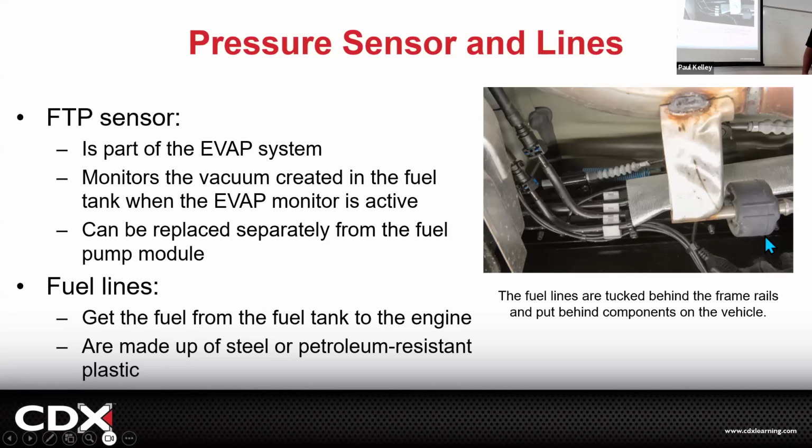Give you a clue. It's got to do with this rubber thing and this thing. Is it just me, or does that look like an exhaust hanger? So if we got fuel lines near the exhaust, is that sketchy? It's normal, sadly. I mean, I'm a little scared, but we run a protective heat shield around the fuel lines to keep it from getting the fuel too hot, to keep vapor lock. If your fuel boils, it'll become a vapor and then it won't start, but also keep it safer.